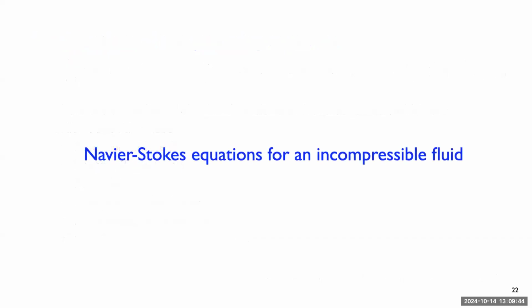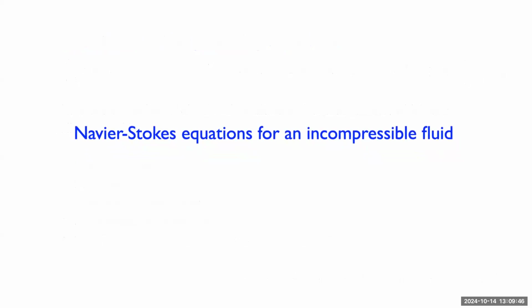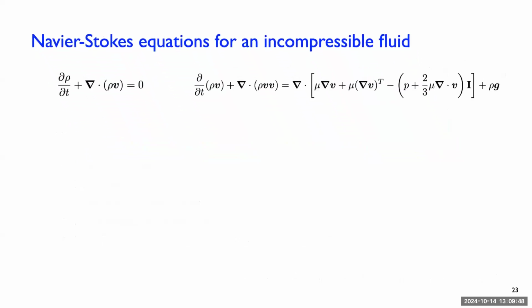Okay, so for the average flux equation for an incompressible flow. For the first lab you've done, we use an incompressible flow solver. So what does that mean? If flow is incompressible, that means the density doesn't change. So this is once again a mathematical modeling assumption. Real fluids and gases are not incompressible, but we're going to assume the density doesn't change. So if the density doesn't change, and if you look at this equation, the density cannot change, then the rate of change with time must be zero, so that must drop out.